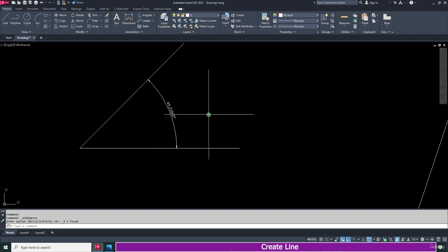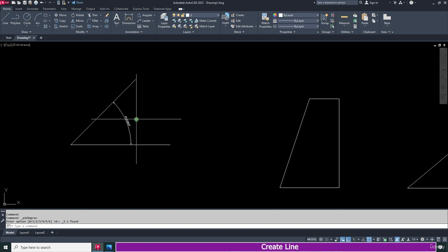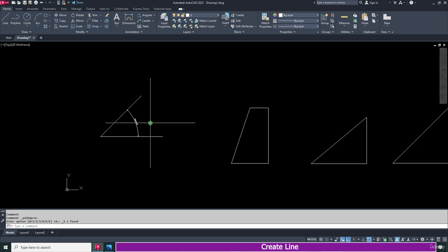But we need to create each and every drawing with 100% perfect dimensions. We don't want any point something like this. Exact 45 we require. So how to create that line? You can create in the polar coordinate system. That coordinate system and all we will learn in coming lectures. I just tell you now here how to create an inclined line.